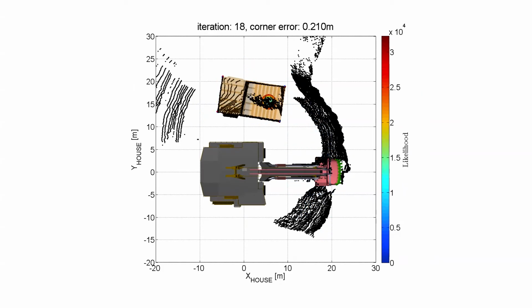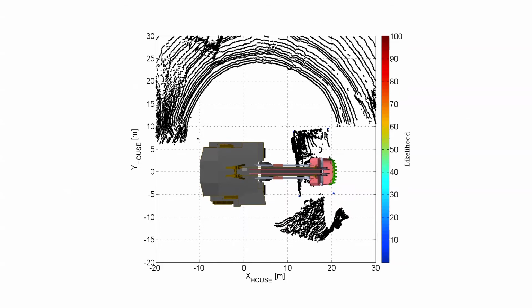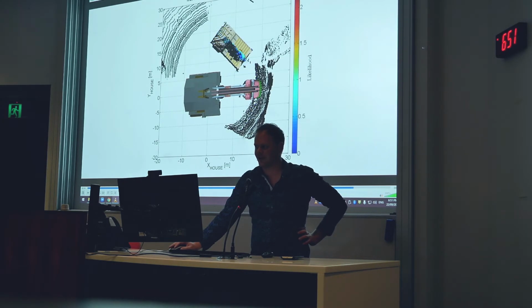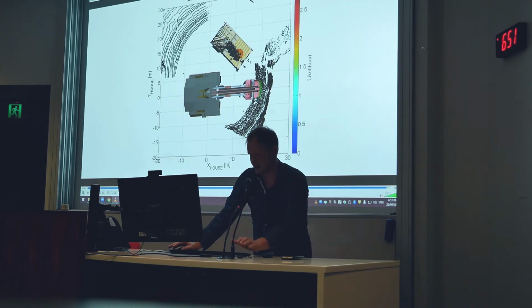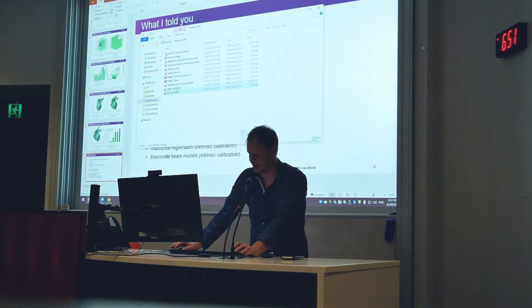Okay, so this is just showing it for a couple of swings of the shovel that we can always find the haul truck no matter where it is, no matter what it's got in the back. Those magnificent rainbow colours are all my hypotheses. The particle filter that I showed you, and that's them converging to a single pose. And that's the sum of the evidence here. You see it gets larger and larger. So that has 200 tons of dirt in the back of it by the end.